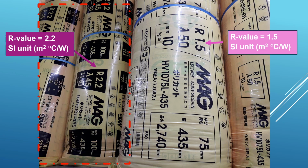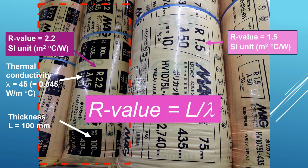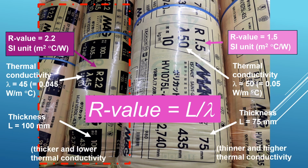Let us see why. If you pay detailed attention to the package, it also gives you the thickness and thermal conductivity of the materials. For the left one, thickness is 100 mm, which is 0.1 meter, and the thermal conductivity is 45, which means 0.045 watt per meter degree Celsius. So R value is 0.1 divided by 0.045, which is 2.2. The one on the right has a thickness of 75 mm and a thermal conductivity of 50, and therefore corresponds to an R value of 1.5. As we see, the one on the left is thicker and also has lower thermal conductivity, so R value is larger.